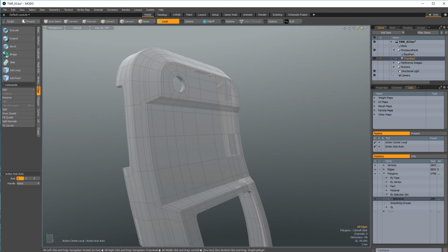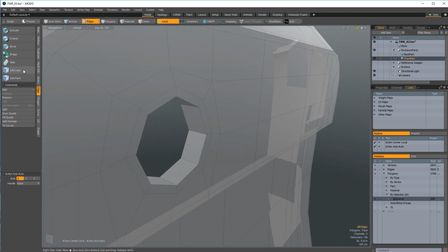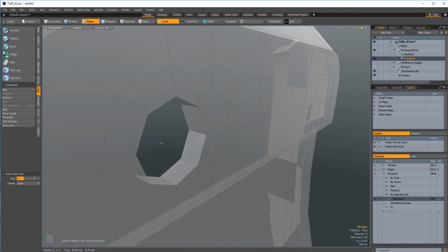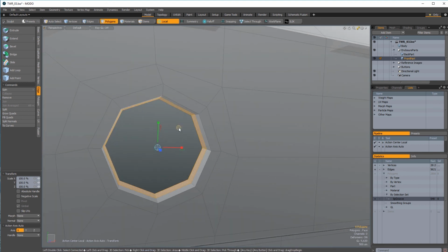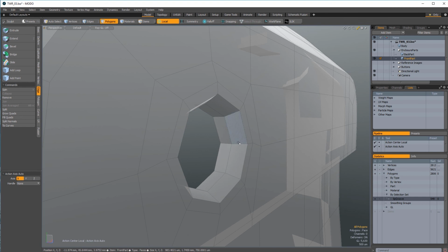And that looks great. Let's just do this one last loop in here. Let's select 2 edges, go Alt-C. Actually, I want to do this one a little bit different. I'm going to add a loop in the center, hold Control, and then I'll grab these interior polygons here, L for loop. I want it to make this look a bit like a chamfer, like so. So we'll need to add Alt-C supporting edges here and now also here.